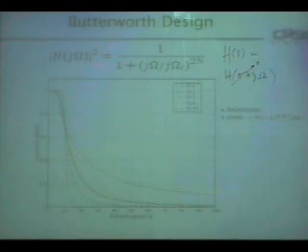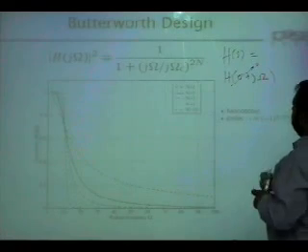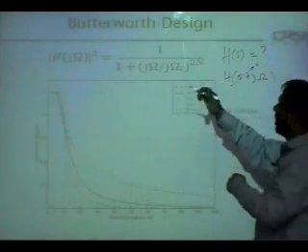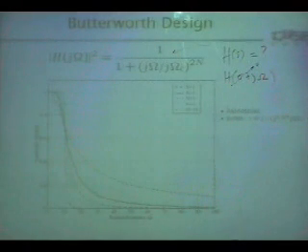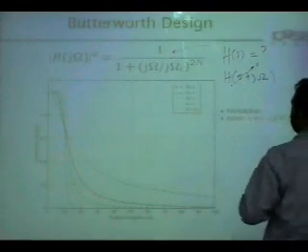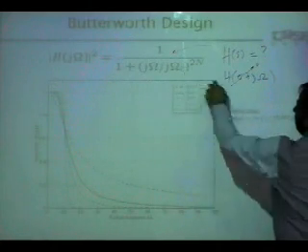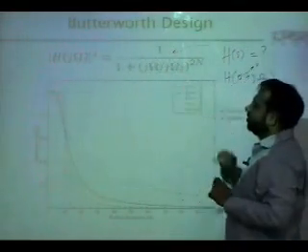So it means I will have a closed form expression for H of S. Once we say spec, it means this. Once we say design, in an analog filter, it means given H of S, like in the discrete domain, design means H of Z. Because H of Z will do what? It will make a difference equation which you implement. In this, H of S will make a differential equation which you implement. H of S is basically a differential equation which you use in analog components to implement. So this is the relationship, and this is the frequency response mathematical expression of a Butterworth filter.